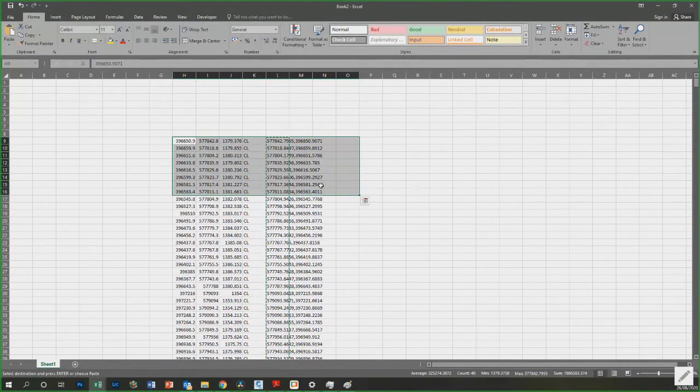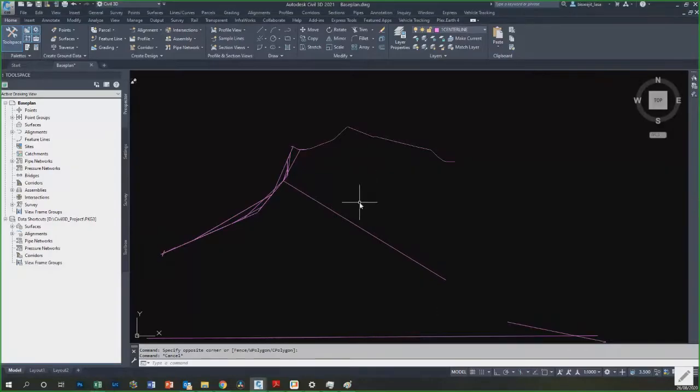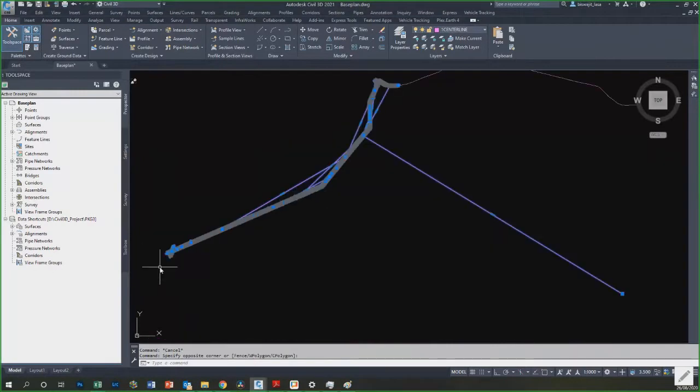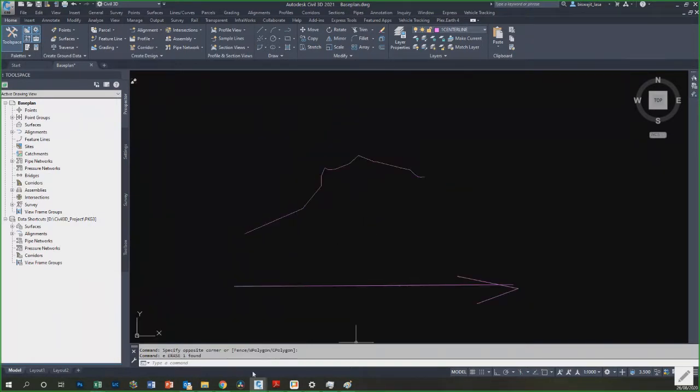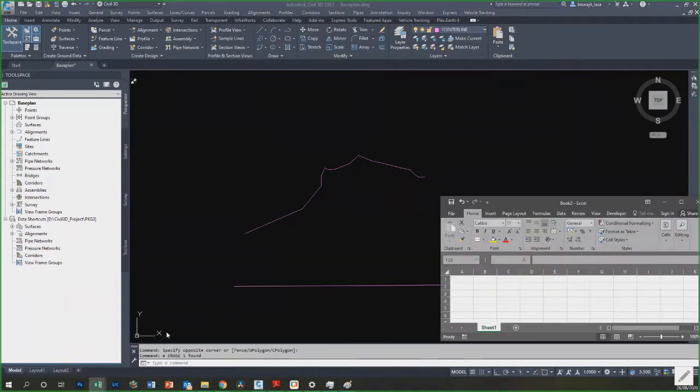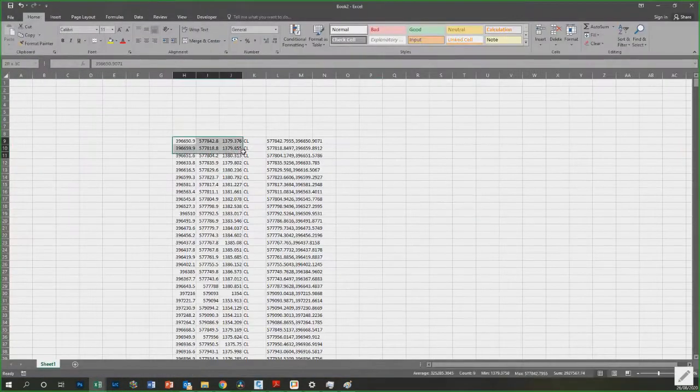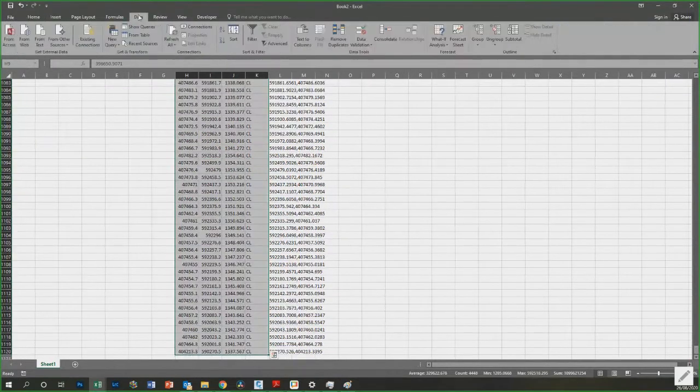There may be two or three teams working together, so they will collect all the data and just bundle them in the order in which they have taken the survey. It might not be in the direction of the chainage. To rectify these errors, it will not be resolved 100%, but predominantly my alignment is increasing in the x direction and then in the y direction. So what I'll do is just simply delete this line, sort this data, go here, sort.